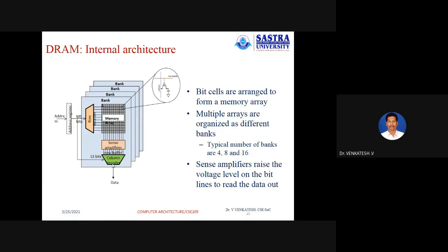But you can ask one doubt there: how does the processor know whether the incoming signal is address or data? For that, during the first cycle, whenever I start that operation, the first cycle, one particular operation will take several cycles. But during the first cycle, whatever the incoming information is, it is always called the address. For example, if it needs 5 T states to complete that operation, the first T state will be used for address and the remaining 4 T states will be used for data. That is why we are going to use the multiplexer. So the same line will be used for address as well as data.